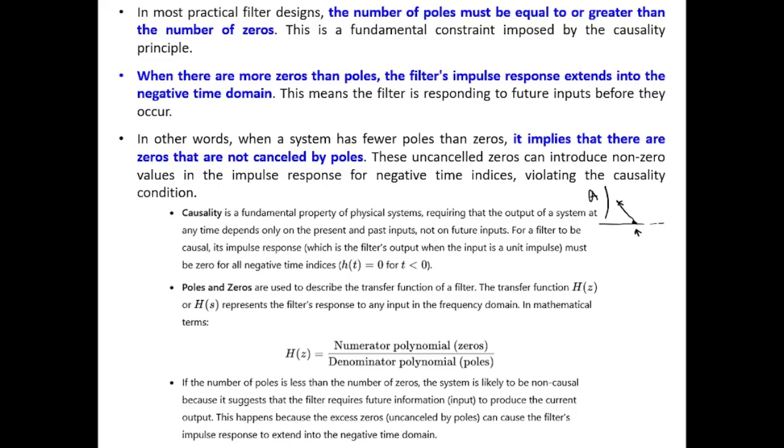On the other hand, in the digital domain, once you have digitized the signal, it is possible. But then, why would you unnecessarily increase your resources? Because putting one pole and one zero extra will increase your multipliers, delays, adders, everything. So your computational burden will increase. So if they cancel each other and you do not want any effect, then just remove that pole or the zero for which you want to suppress the gain property.